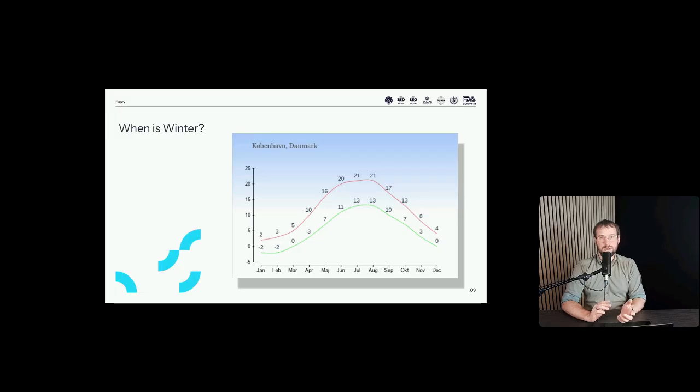But when we are conducting a mapping study, that is often done during a period of, let's say, 1, maybe 2 weeks for larger facilities. And for smaller units, it might be as low as 1 or 2 days. So how do we ensure that we capture representative temperatures? It's really hard to answer that question because you do not know whether that will be representative of all the cold winters that we have. A good rule of thumb is that if you stay within 5 degrees of what you expect to be your lowest temperature, that should pretty much cover all the different scenarios that you would expect during a year. But again, it's about risk appetite, and it's about having a well understood risk assessment.